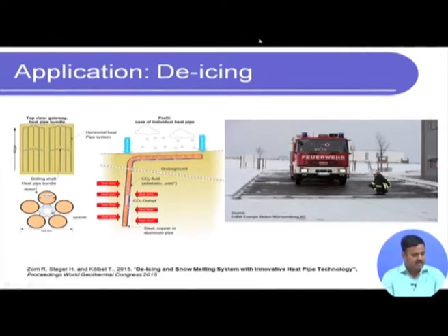But this one, if you look at it, think about it, it is snowing, but what about if you go down in the underground, what happens at the depths, if you go deep, the temperature is higher. Okay. So therefore what they are trying to do is they are using heat pipes over here, okay, steel, copper or aluminum heat pipe, and as you go underground over here the temperature is much higher compared to what is on the road. So it is a heat pipe with a bend. So the evaporator section in this case over here is deep down into the earth's crust. I mean not deep down, I mean a few meters, and the condenser section or the cold section is right below the soil or right below the road in this case.